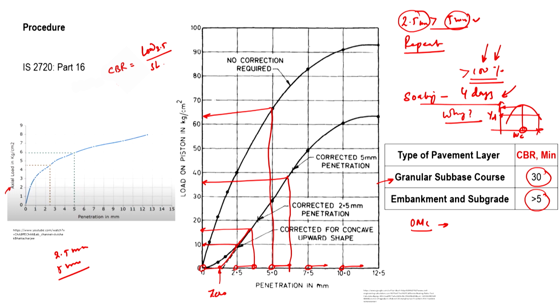So, if we do the design considering the strongest state, this design may not be very conservative, considering that the soil has to be constructed at locations where we anticipate more change in the moisture content of the subgrade soil. That is why the codal provision recommends that, to make the design conservative, we see what the CBR of the soil will be in the worst state of moisture content, and we use that CBR in the design process to calculate the thickness of different layers in the pavement.